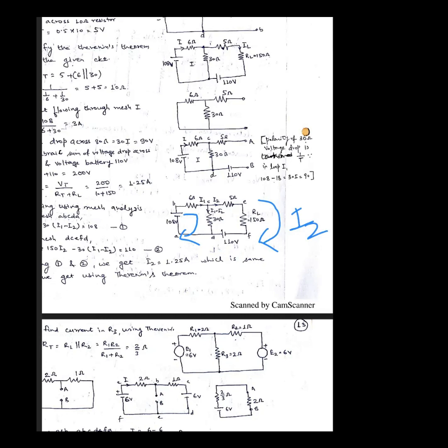Okay, so when the C node is there, here the KCL will be applied. I2 current is flowing in this fashion. Okay, and I1 current is the incoming current and I2 current is the outgoing current. So the current which will be flowing in the vertical branch will be I1 minus I2. Okay, is this clear? Similar types of problems we have done already.